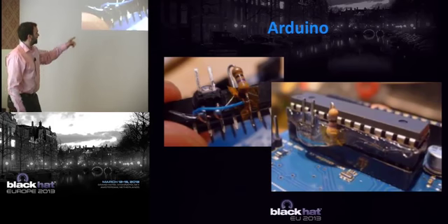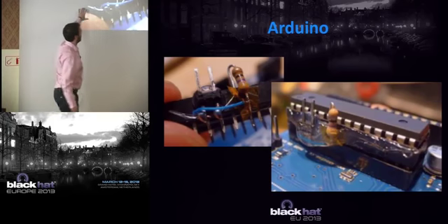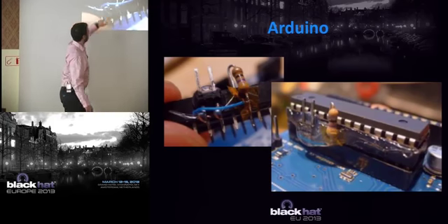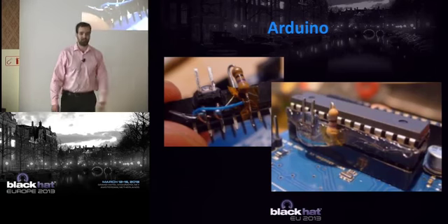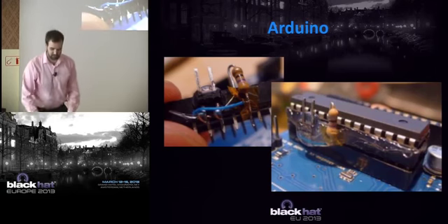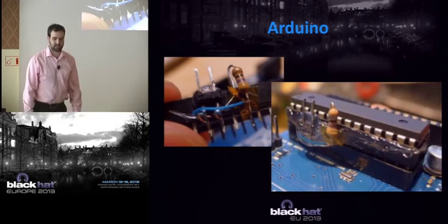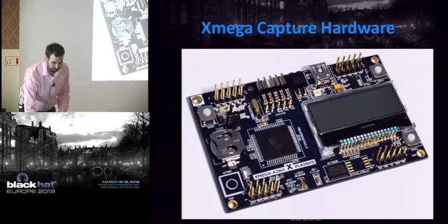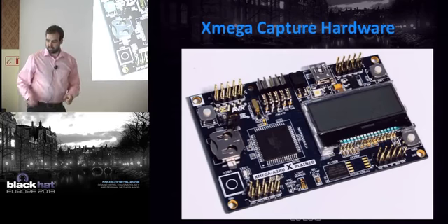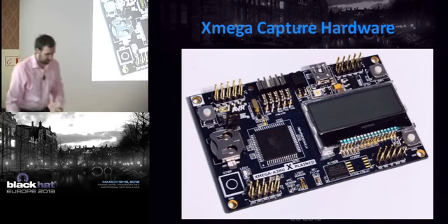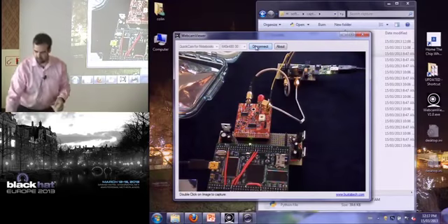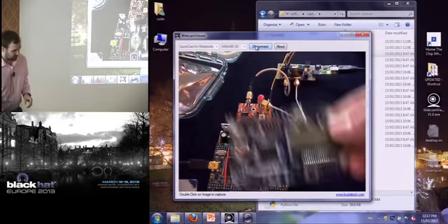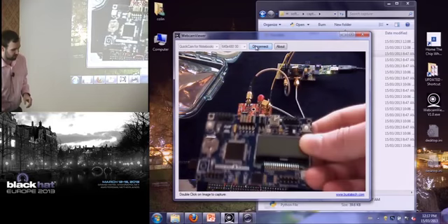And I've sort of hacked together a DIP socket with a resistor in one of the power lines. And then that resistor you connect up to your scope. So that's a sort of very low-cost type target. Another interesting thing that's not working right now, but at some point may, this is getting even cheaper. This is an XMega, another AVR microcontroller.